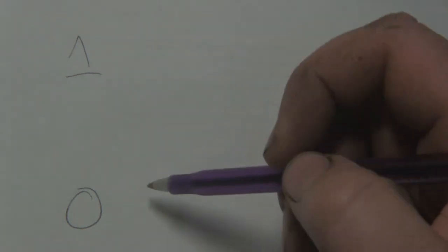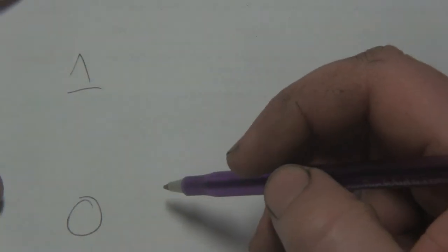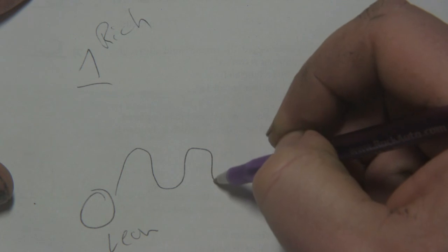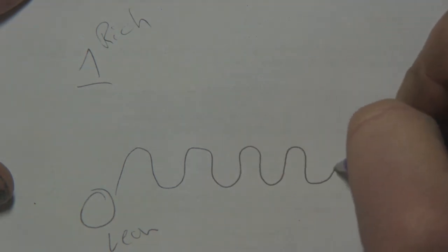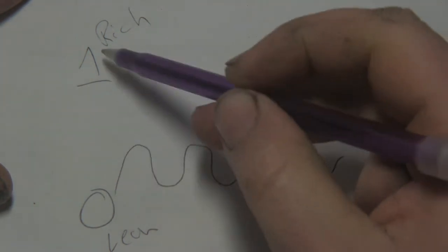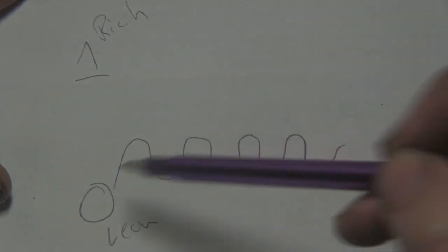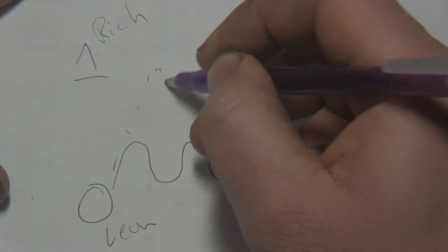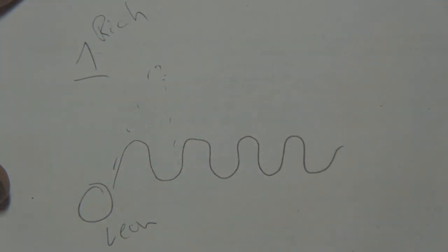And so in a case like this is part of the reason why I say scan tool data is still good, and I still like to use scan tool data. What you're going to see here on the 0 to 1 volt scale, remember, this is the rich side, this is the lean side, is a voltage range that's kind of cycling up and down, but not making it to the full rich, hovering down at the lean side. You might see the occasional point where we make it up to 1 and then come back down, then hover down low again.